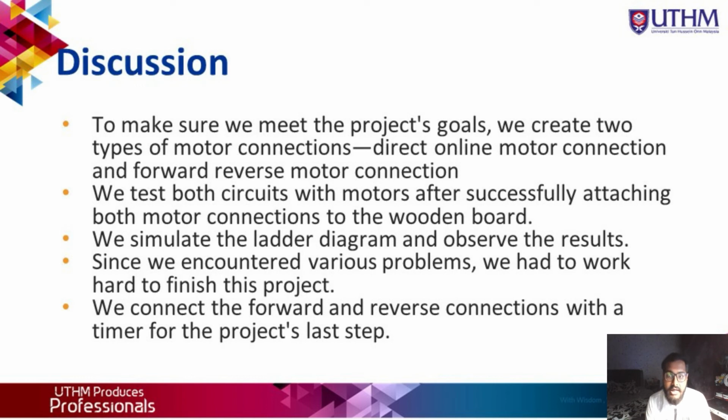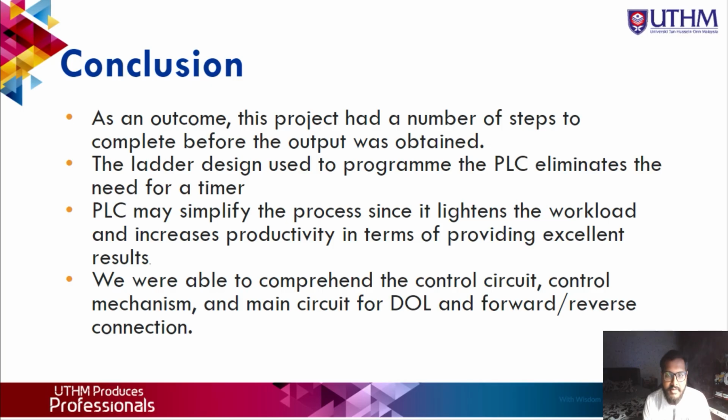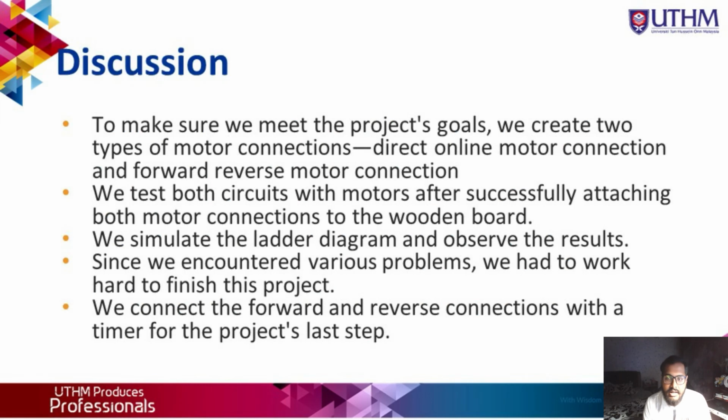A device that controls the flow of electric power to a motor is designed to safely start and stop a motor and provide overload protection. Unlike the forward-reverse motor starter, direct online does not reduce the starting current of the motor and causes unnecessary torque, which supports our decision to use forward reverse connection over direct online connection.